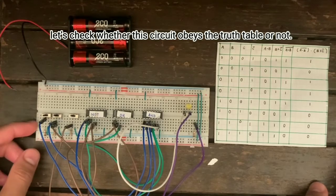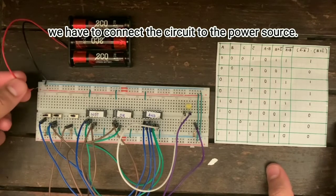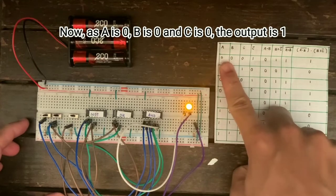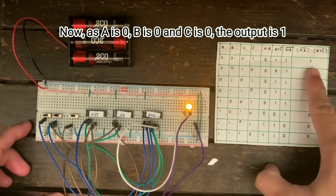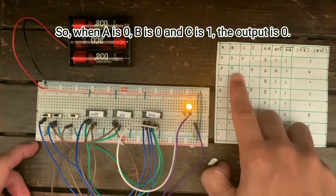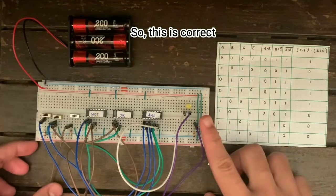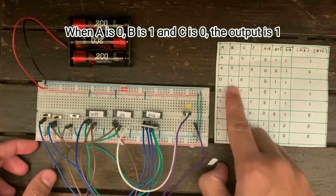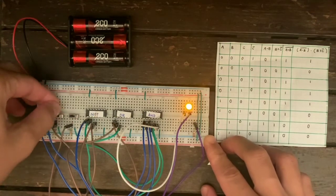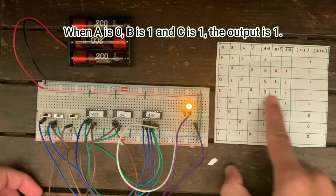Okay, so now let's check whether this circuit obeys the truth table or not. So first, we have to connect the circuit to the power source. Now, as A is 0, B is 0 and C is 0, the output is 1. So, the LED is light up. So when A is 0, B is 0 and C is 1, the output is 0. So this is correct. When A is 0, B is 1 and C is 0, the output is 1. So it is correct. When A is 0, B is 1 and C is 1, the output is 1.